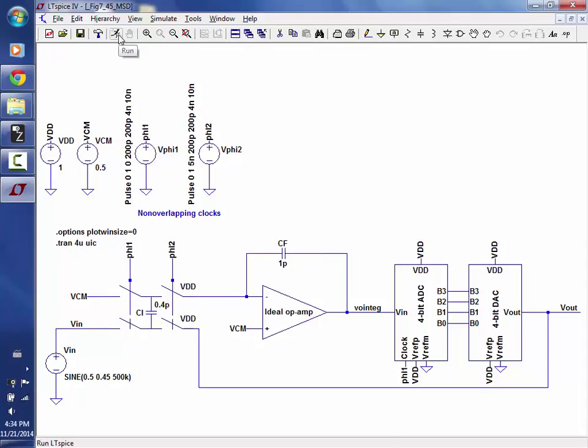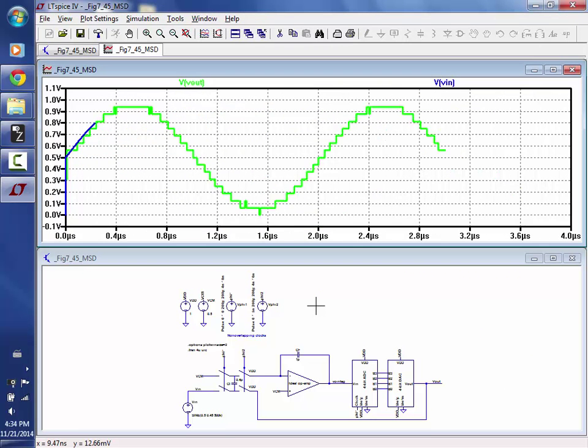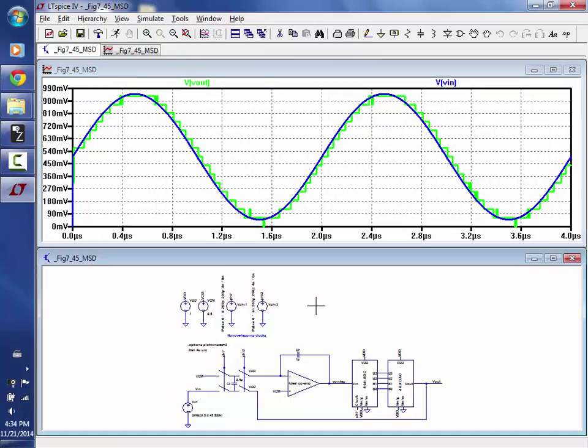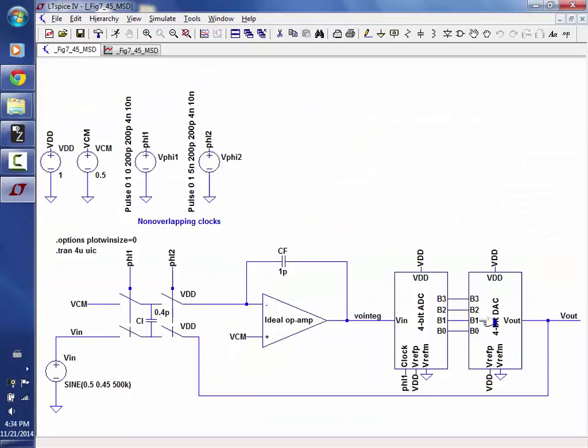So there, does everybody see? And I'm using the output of the DAC as my output so I can see what's happening. And then you see, oh okay, there it is. Yeah, it's better. It's a 4-bit DAC. All right, so there's a couple issues here. Does everybody understand the basic idea? So the average you feed back is closer here, but it's not 1 bit like we had before. So the issue here is